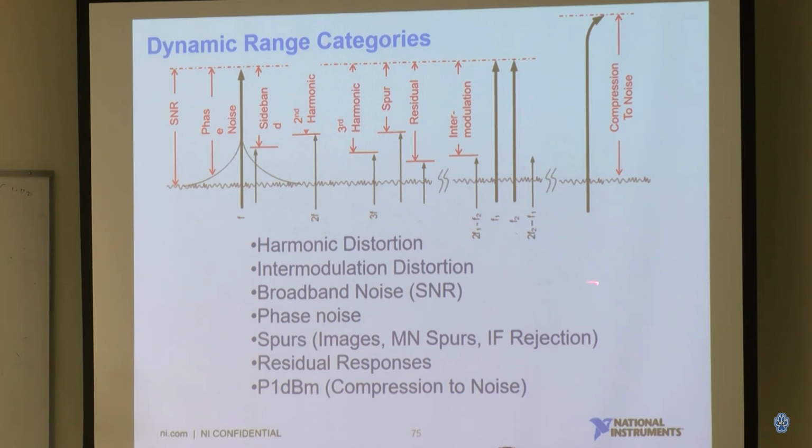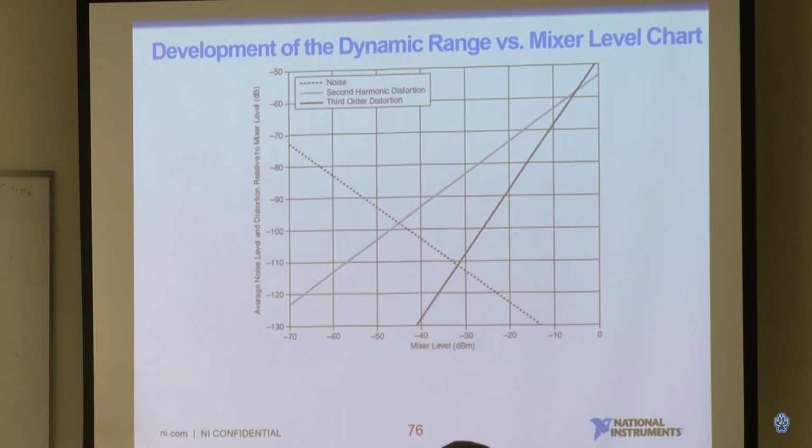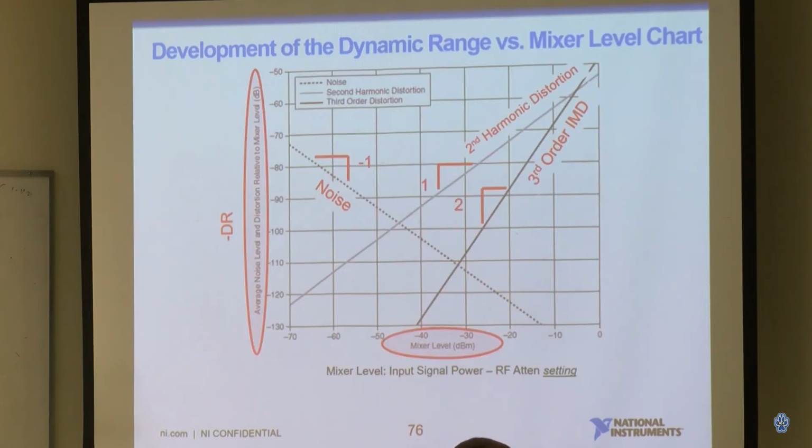And I think I covered some of this already, like harmonics and phase noise. And spurs means you have additional signals you don't want, when you have a generator signal or when you're trying to analyze some signal. And this one is the dynamic range chart with your mixer level. You will see in some data sheets, like for a mixer, they can tell you what power level gives the best linear mode and at what power level your mixers start to have more and more distortion products.